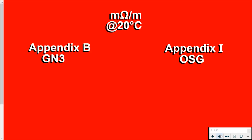Like previously, we're going to be using Table B1 in Appendix B in Guidance Note 3 and Table I1 in Appendix I in the On-Site Guide, utilising the milliohm per metre values for these cables at 20 degrees C. Okay, so that's the resistance of the cables per metre at 20 degrees C.